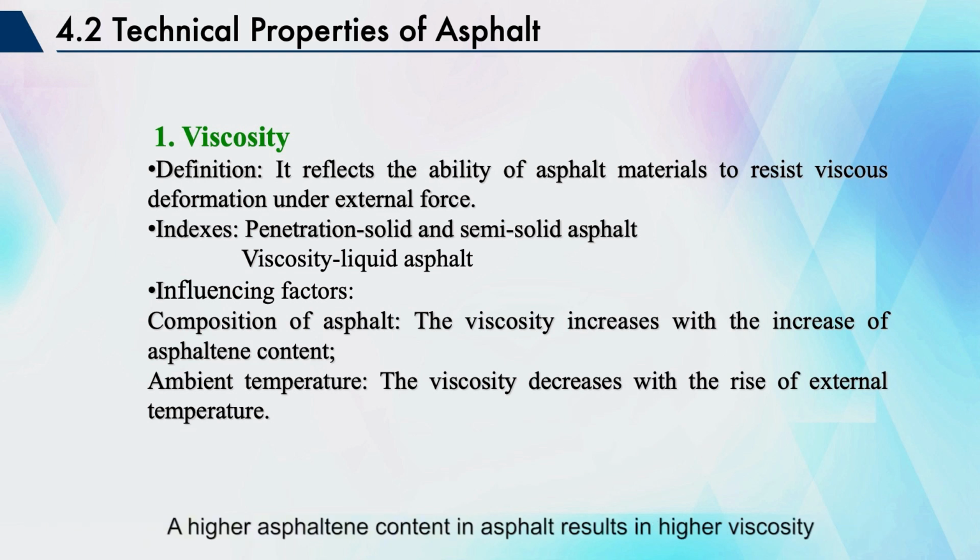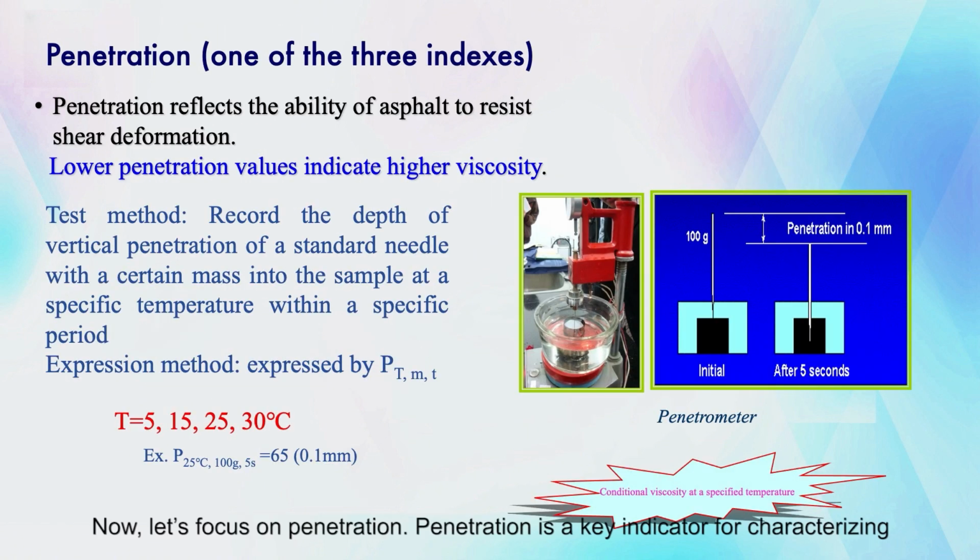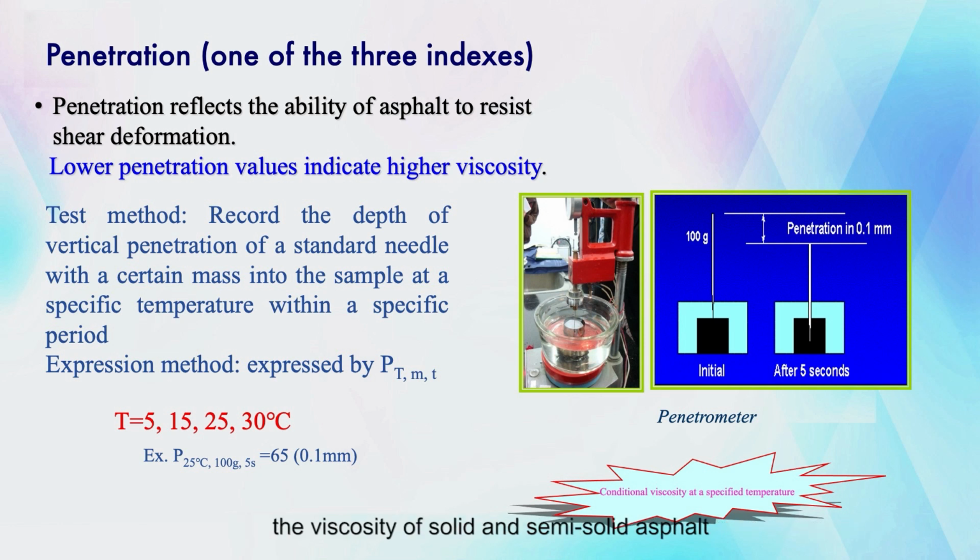A higher asphaltene content in asphalt results in higher viscosity. Additionally, external temperature affects viscosity. Higher temperatures lead to decreased viscosity. Now, let's focus on penetration. Penetration is a key indicator for characterizing the viscosity of solid and semi-solid asphalt.